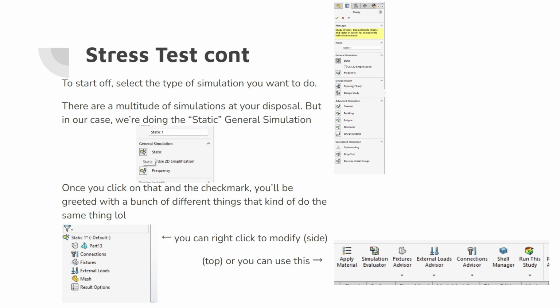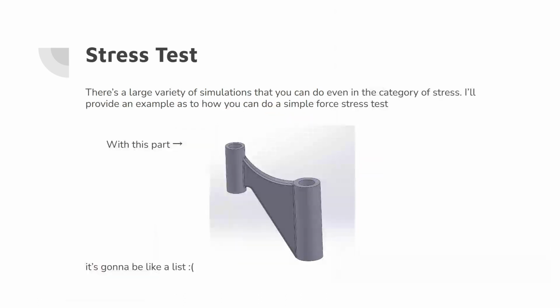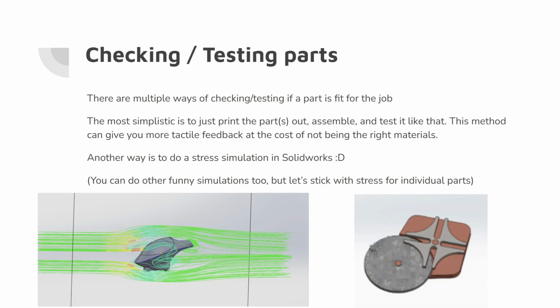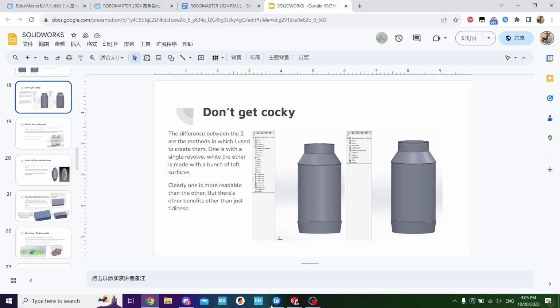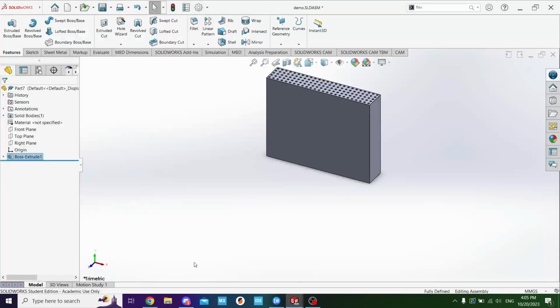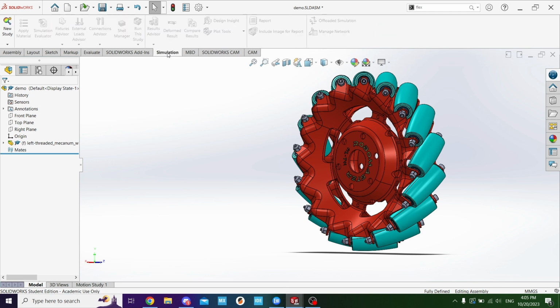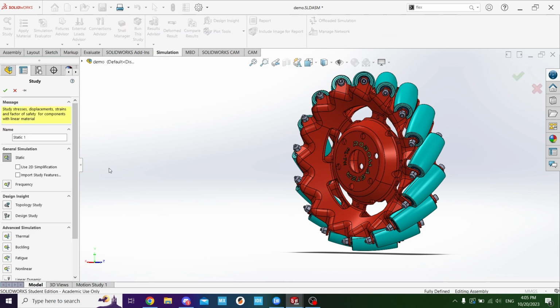Simulations tab, right? On the top, there's a start simulation. What was it? Wait, go back. I forgot how it looked again. No, go all the way back to the simulations top bar. I might as well just find it in SolidWorks. Yeah, just find it in SolidWorks. Simulations, new study, right? So you click on new study. Let's go through it with you.